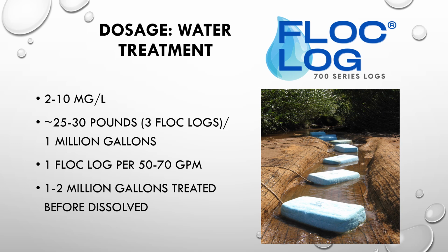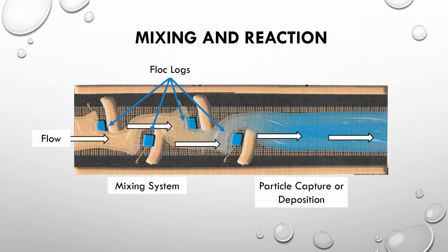So they will fully dissolve kind of like a soap on a rope. And once it gets down to that skeleton area, it's probably time to replace the logs if you want to continue treating that water. So now we've kind of talked about dosing and how important that is. We've talked a bit about mixing and reaction, but we really cannot say enough about how important mixing is.